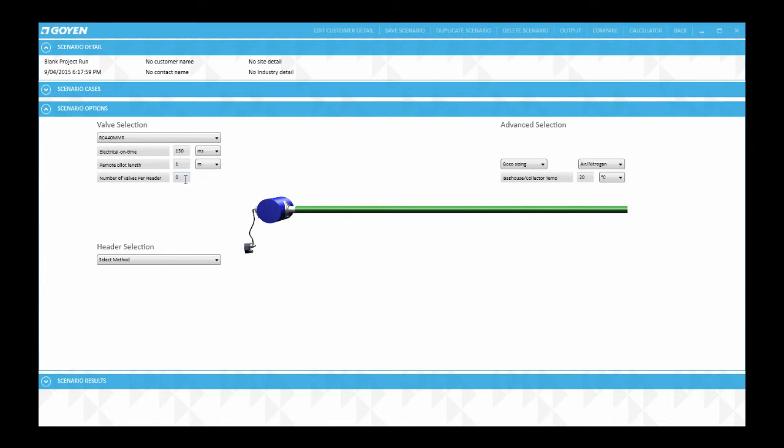They have an interconnecting pipe passing through the header from the valve body to the outlet to the opposite side of the header tank. This input is used to subtract the volume of the connecting pipe passing through the header from the header volume without any valves. This leaves the net volume. The calculation of the header volume is then based on the header net volume with the valves mounted to the header. Quite simply, we can say that the net volume is the whole header volume minus that volume from the interconnecting pipe.